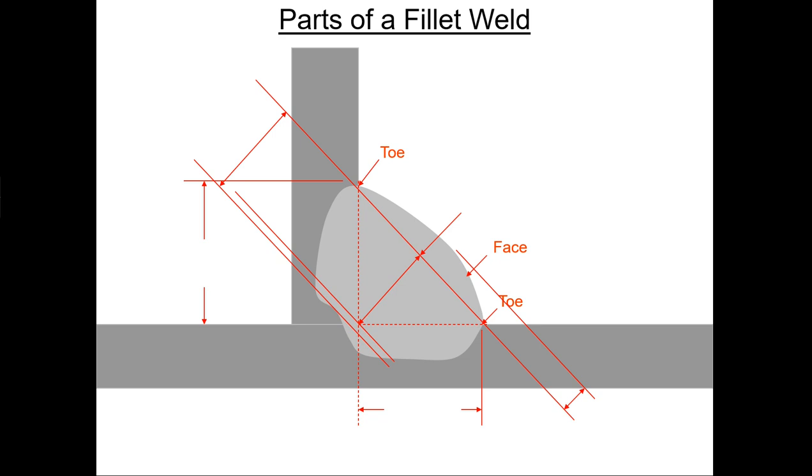If I'm talking to automotive people right now, if it happens to be somebody in automotive production, stop everything if you start seeing cracks develop. Something's changed inside the process, and it's usually very serious. If you've made a whole pile of these welds and all of a sudden it's cracking, it could be base metal issues. It could be a contaminant on the material. Please don't just try to push through it. Make sure that the controlling people around there who are responsible for the welding know that this is happening.